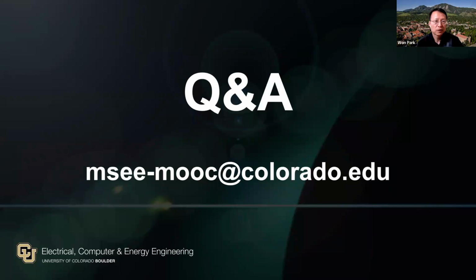I do touch upon that in my semiconductor devices specialization. I do not go in depth in describing the details of the lithography process, but in discussing CMOS devices, introducing the basic device structures and how CMOS works, I do touch upon how they are fabricated through the standard lithography process. I do not mention the deep UV process specifically, but they basically operate on the same principle. They simply use shorter wavelength.